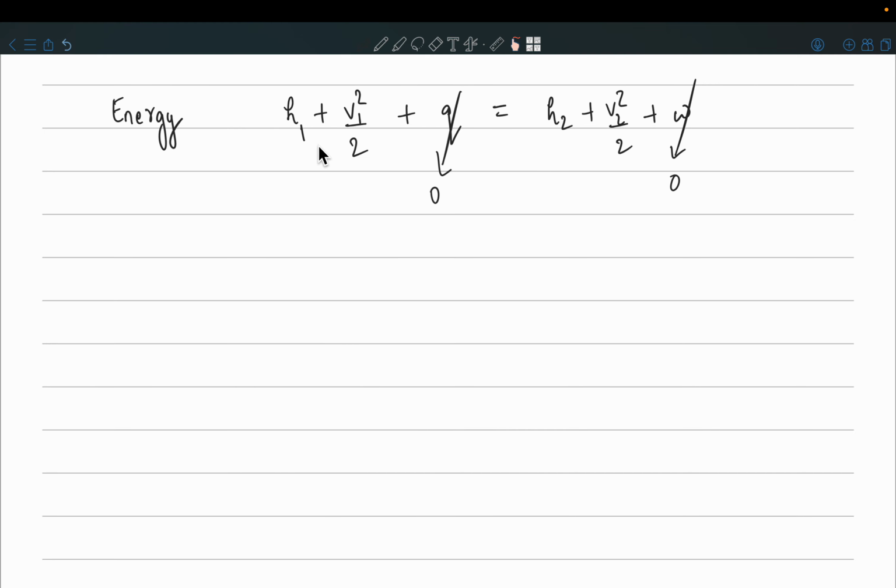So right now we have that the total enthalpy remains the same across a normal shock. From this we can immediately conclude, because there is no change in the composition of the fluid, that T01 is equal to T02.